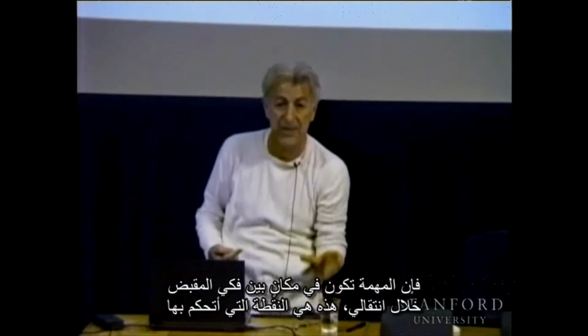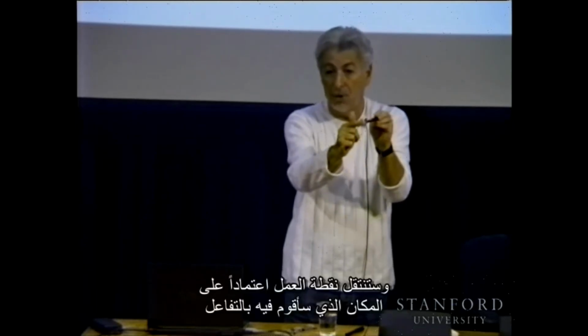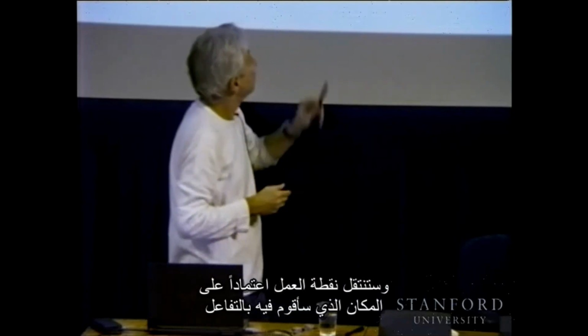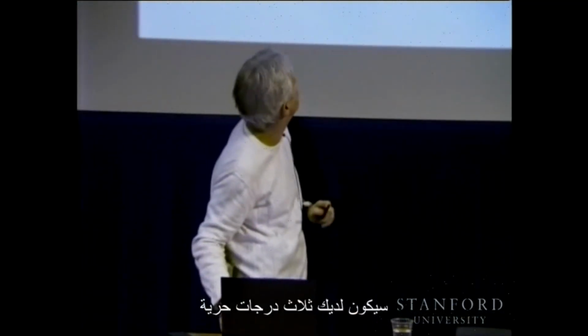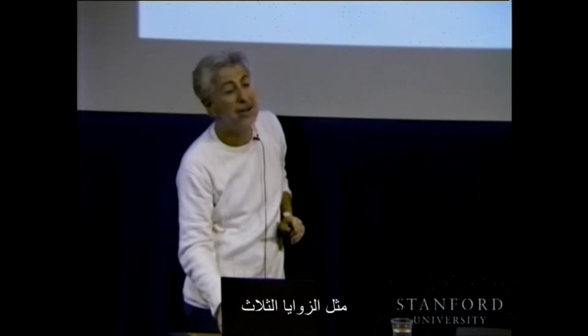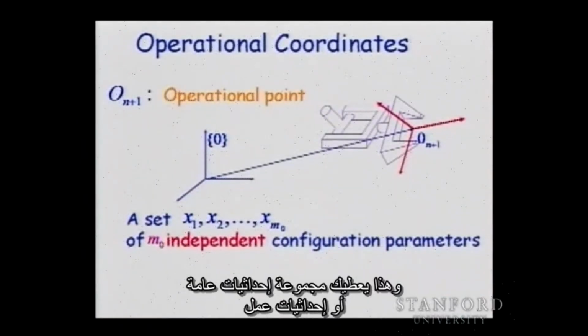As I move, this is the point I'm controlling. But if I have a tool, the task will be here, and the operational point would move depending on where I'm going to do the interaction. So this is the first definition: operational point. So you have 3 degrees of freedom, and then you add 3 degrees of freedom, like the 3 angles, to form a set of independent parameters, and that gives you a set of generalized coordinates or operational coordinates.